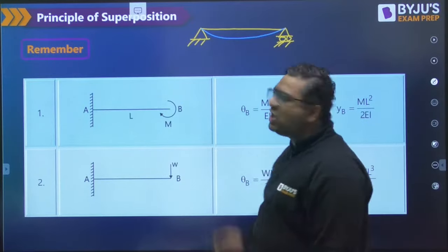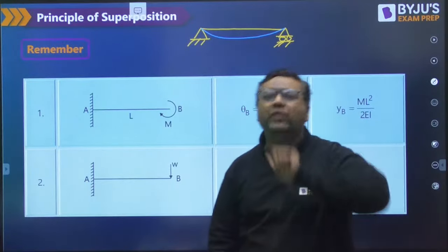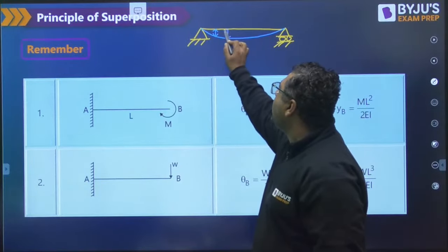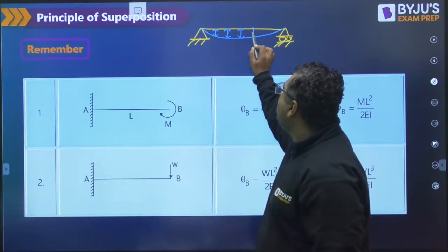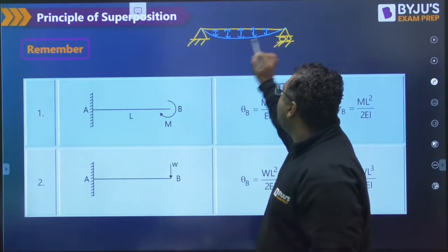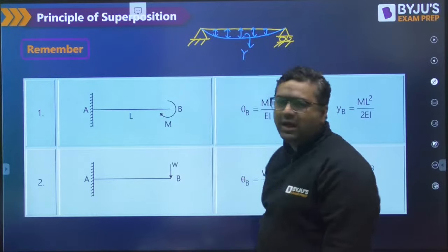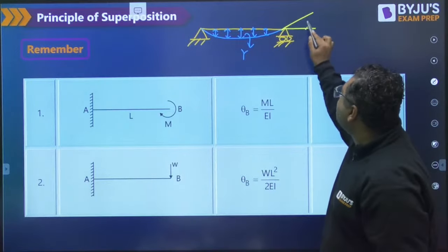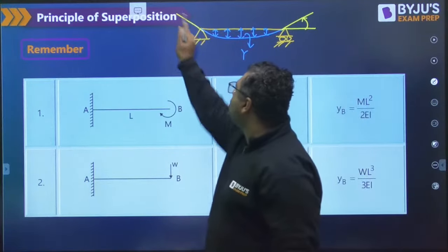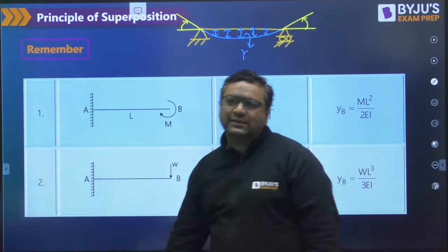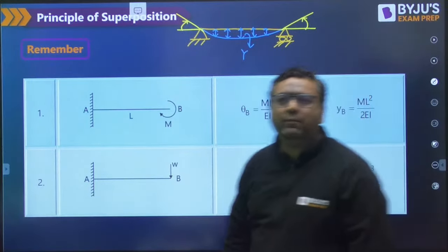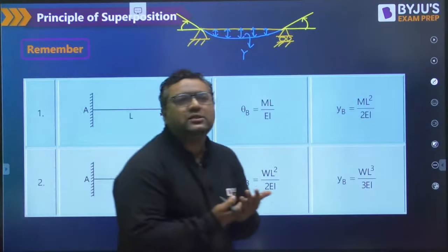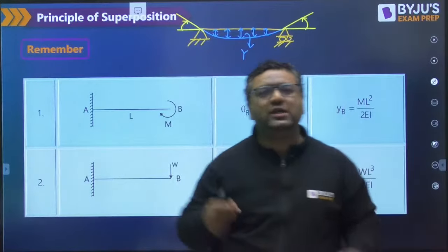So if you see, this deviation is happening in two ways. One is that it is deviated from the longitudinal axis in the lateral direction. So my dear, this lateral deviation of the beam from its longitudinal axis is said to be deflection. And similarly, if you see, it is making some angle with the x-axis. So this angular deviation with respect to the longitudinal axis is said to be slope. Yes, Bablu Saha, good evening dear. So this is said to be the slope. So angular deviation is slope and lateral deviation is deflection.